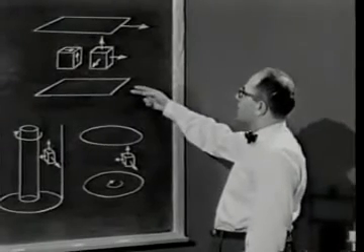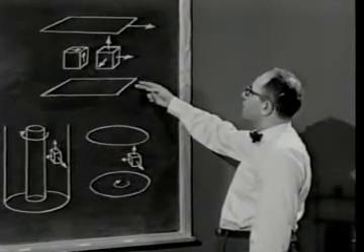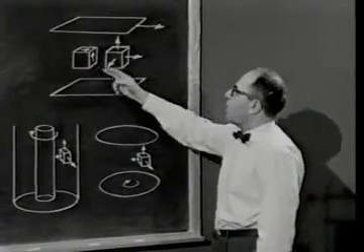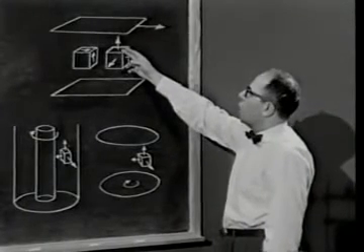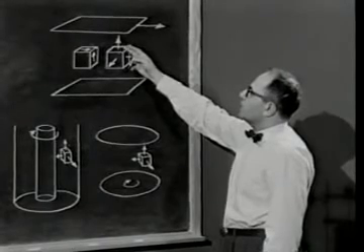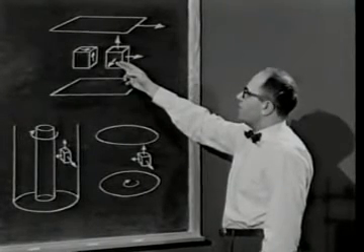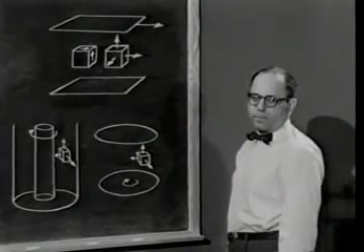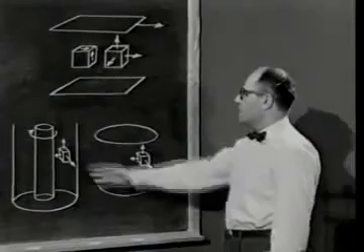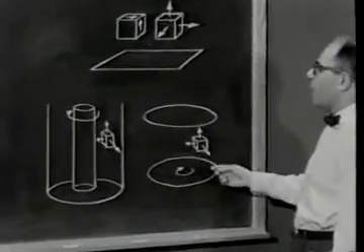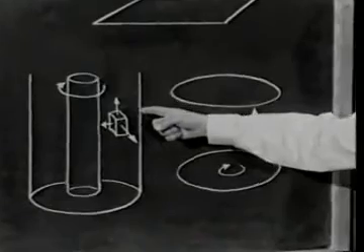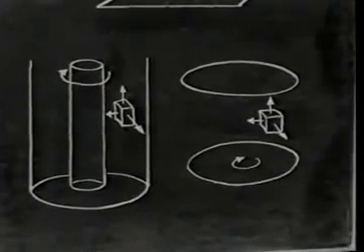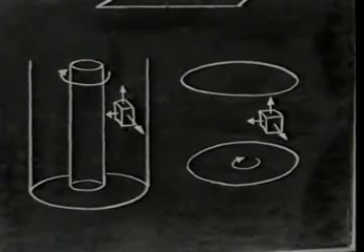This diagram represents steady, simple shearing between infinite parallel plates. In addition to the shear stresses, there are also normal stresses. For the Newtonian fluid, the normal stresses in these three directions are all the same. With non-linearity in general, they will not be the same. We have just seen some experiments in cylindrical geometries. It is the inequality of the normal stresses on this infinitesimal volume element that gives rise to the normal stress phenomena which we have just observed.